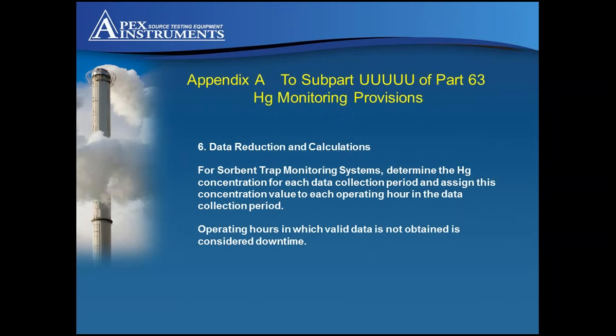Section 6 outlines data reduction. It's quite specific on how to report data and carry out calculations, to report in hourly averages for any operating hour. Any hours without valid data are considered as downtime.